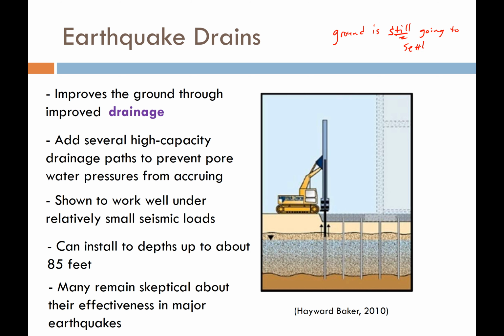You're not eliminating that, because what you're doing is increasing the water's ability to get out of the ground. So you're going to have some volumetric deformation, and you're going to see some settlement. The only catch is it's not as much settlement as you would get if the soil liquefied. So this ground is still going to settle. It's just not going to settle as much. So we still need a whole lot of research on this method, particularly in the field in a major earthquake.